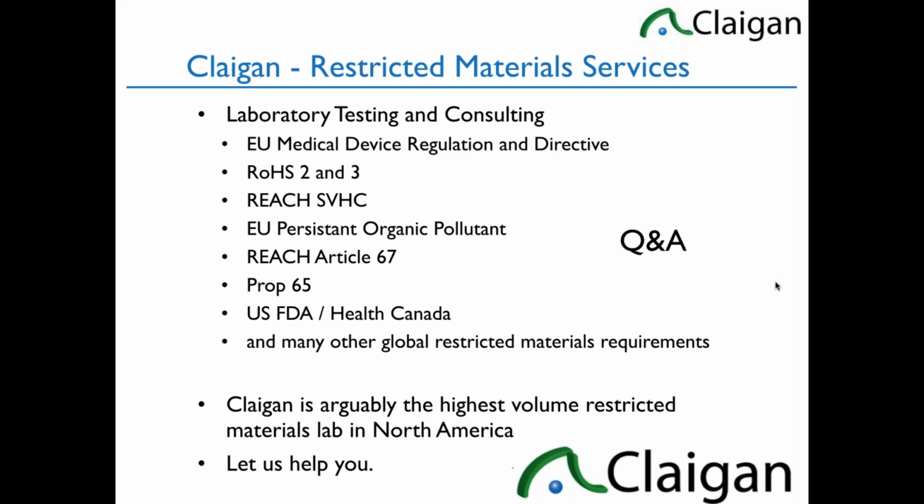RoHS doesn't just apply to electronic components. If a device has electronic function, everything that's intended to stay with the device for its lifetime, with a few little exceptions, is in scope of the materials restrictions of RoHS. So if you have a carrying case for your drill, the carrying case is intended to stay with the product for its lifetime, and it's normally in scope of RoHS.